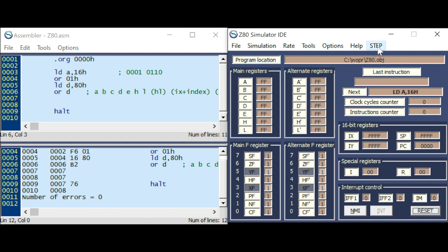Again, 16, adding 1, zero flag 0, parity flag is 1, because 1 is 1 bit, and 7 is 3 bits, that are together 4 bits, that's even. 80 is loaded to D, and that's 97. So the sign flag is 1, because the highest bit is set, and it could be a negative number. Zero flag is 0, and the parity flag is 0 because 9 is 8 and 1, that are two 1 bits, and 7 are 3 bits, that's 4, 2 and 1. Together they are 5 bits. That's not even, that's why parity flag is 0.